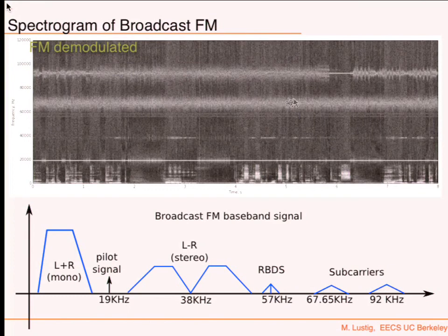But you see, these are low bandwidth FM modulation. It's kind of like double FM, because this will be FM modulated and transmitted. Once you demodulate, this is still FM modulated. You have to FM demodulate that again in order to recover this. Do those subcarriers contain all these components? No, they don't have enough bandwidth to do that. Those would be like 5 kilohertz, 10 kilohertz bandwidth, so it's not high-quality audio, of course.